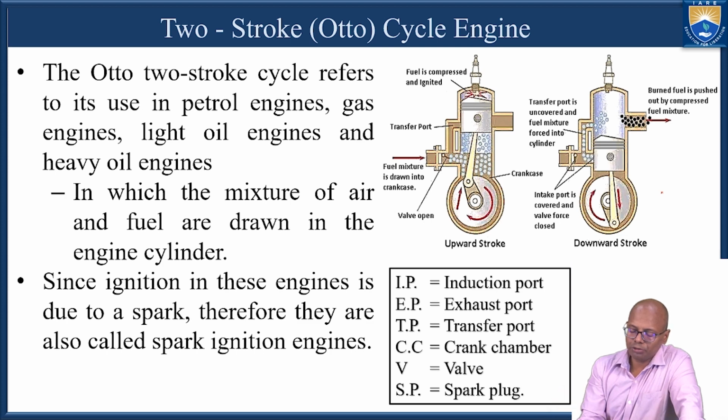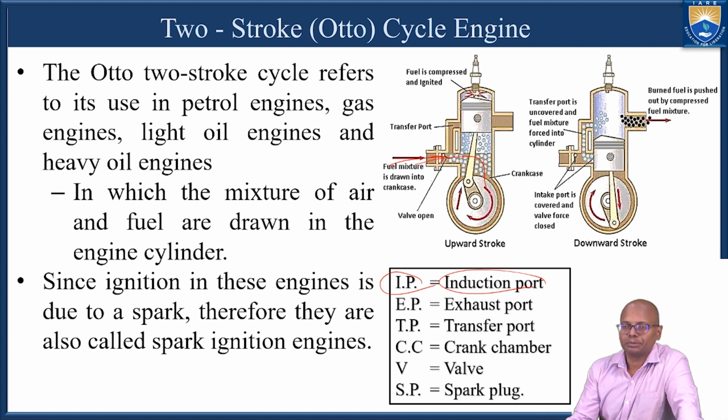Now, if you see the parts, the inlet port or induction port is there, through which the fresh charge is taken inside this crankcase. There is an exhaust port, through which all the exhaust gases are thrown away.